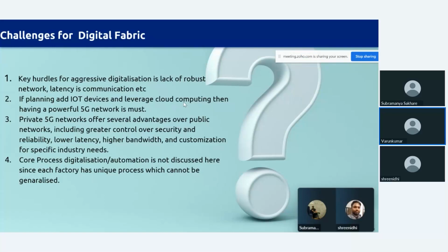When it comes to the existing infrastructure within the factory, there is the network which has to be available. We see a lot of factories in very remote conditions where there is no proper internet connection. We want to implement IoT and have a digital twin, but there is no internet communication available there. There is a lot of latency in the communication, and not only is there no public internet, there is no private intranet either. Sometimes we need to propose starting from that, where we have to create a private network, and then all the communications from device to device and device to human interface also have a lot of latencies. So we have to think of certain edge computing mechanisms as well to overcome that kind of latency.